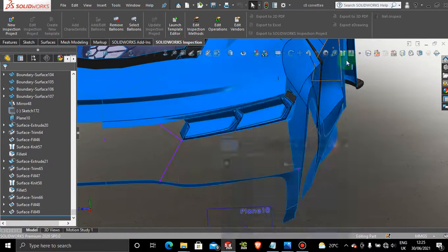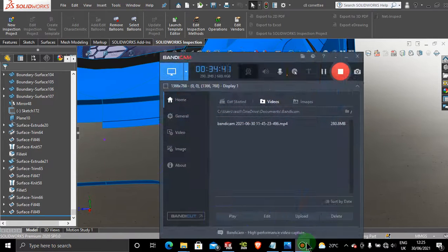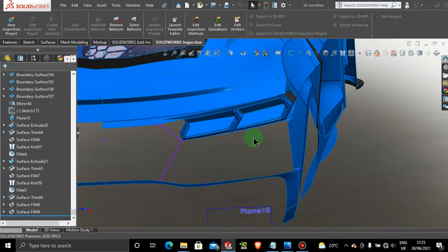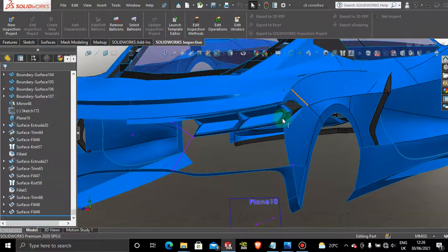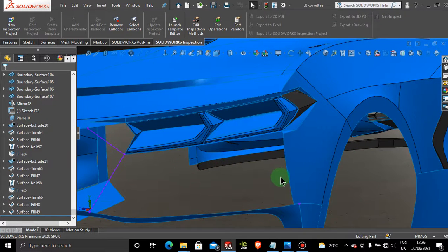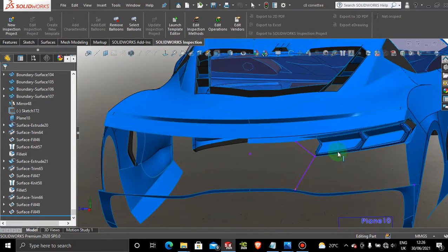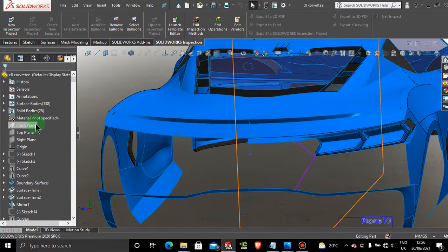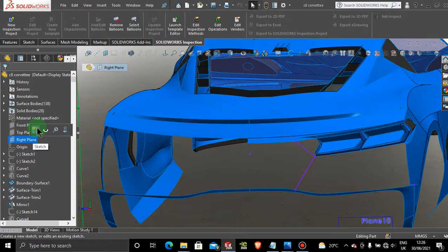All right, so in case you wonder how I got rid of the pink line, it's a common fact in SolidWorks. I just saved everything and I exited and restarted the program. All right, so we're going to do the same thing on this side, on this area here. So it's going to be a map or create a sketch on the right,